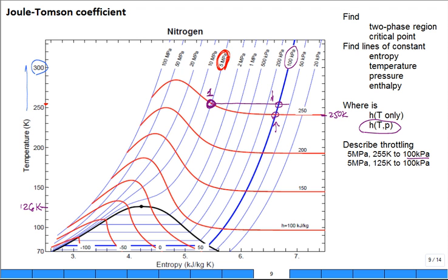125 Kelvin. Find that spot. Where is that going to be on the diagram? So it's right about the same temperature as the critical point, and it's about right here. Maybe not on that red line of zero enthalpy, because the enthalpy is negative 50, then negative 100, but let's say it's on that red line.